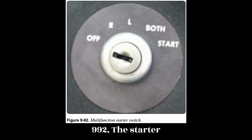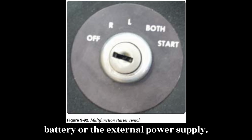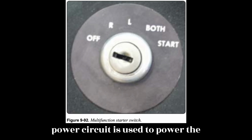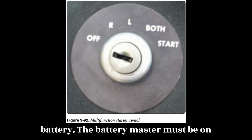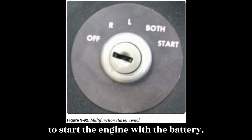Figure 9.92. The starter can be powered by either the aircraft battery or the external power supply. Often when the aircraft battery is weak or in need of charging, the external power circuit is used to power the starter. During most typical operations, the starter is powered by the aircraft battery. The battery master must be on and the master solenoid closed in order to start the engine with the battery.